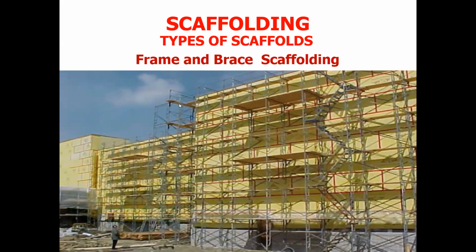When you look towards your left again, you will see another staircase. If you look closely, you will see the diagonal members. You see the standards standing, you see the ledgers, and you also see the diagonal members. These are the members that give stiffness to the entire system.